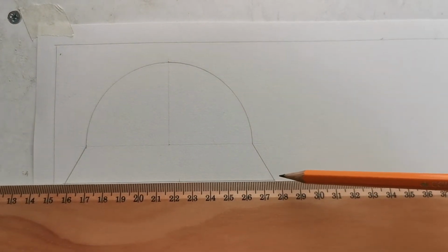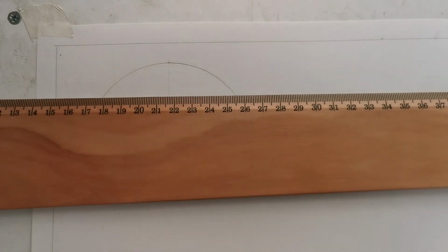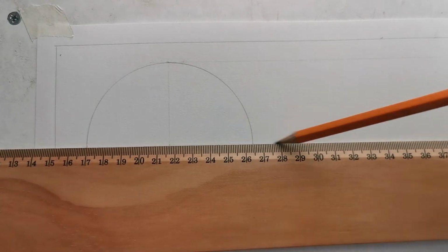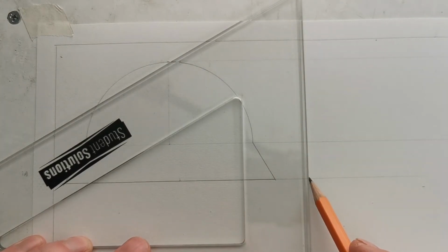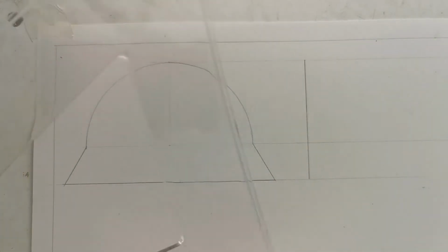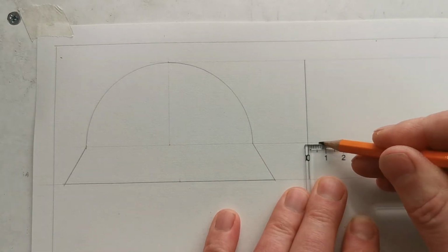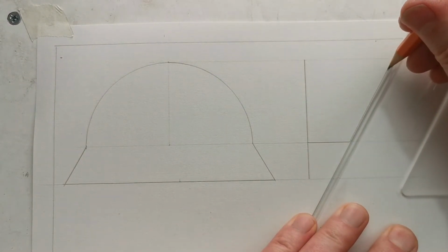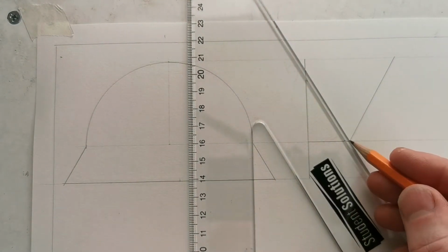So the next thing we want to do here is our end view. So it's vertical up the left side. Just bring across these heights. So just leave a small gap between them. It doesn't really matter how much. So it's vertical up the left, and it sticks out 24 here, and 60-degree slopes. Nice question, because there weren't that many measurements involved in setting it up. So there.